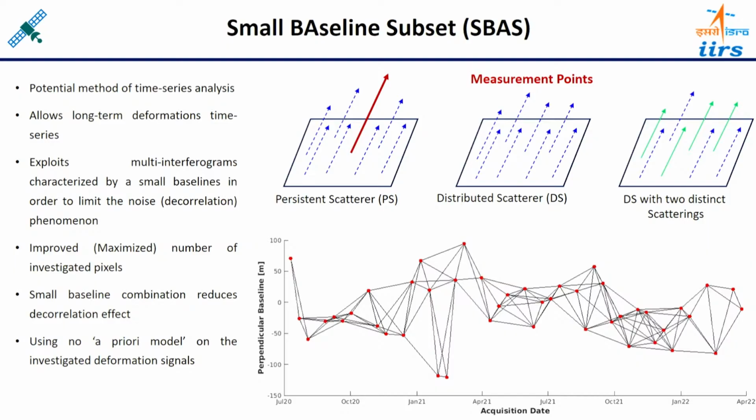By using this concept, you can reduce the number of pairs from 4950 to, let us say, less than 1000, or to the numbers which your computer is capable of processing. So people are not processing NC2 interferograms, they are processing much less than NC2. Let us say out of 5000 we are processing only 500 or 600 interferograms, and the others we are ignoring.